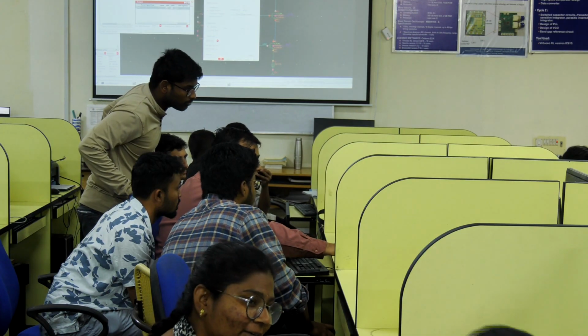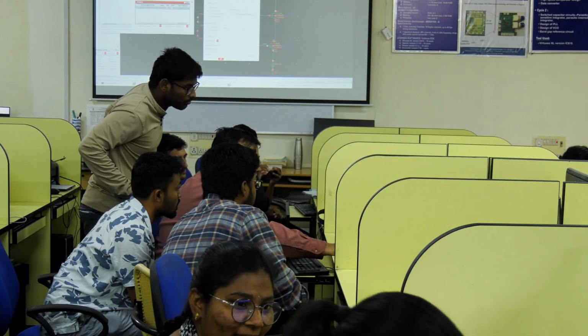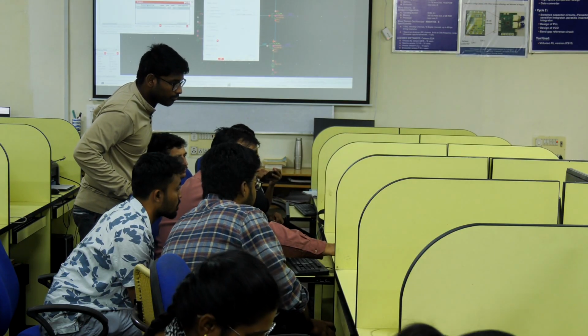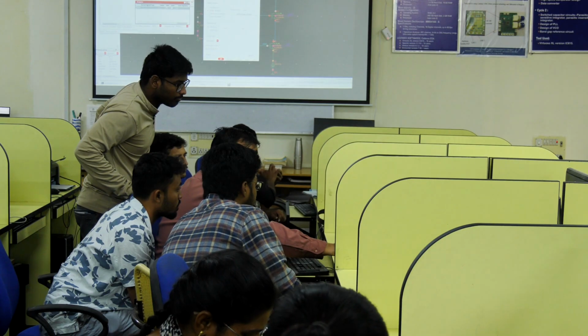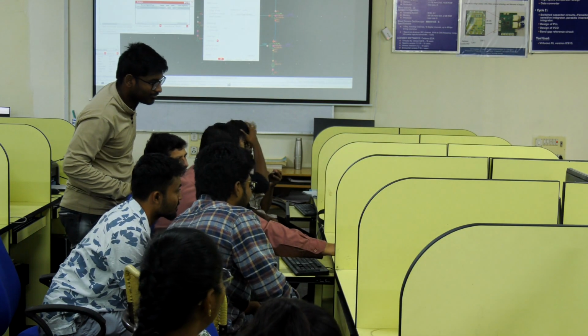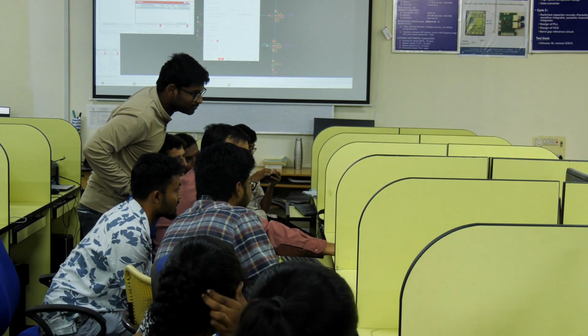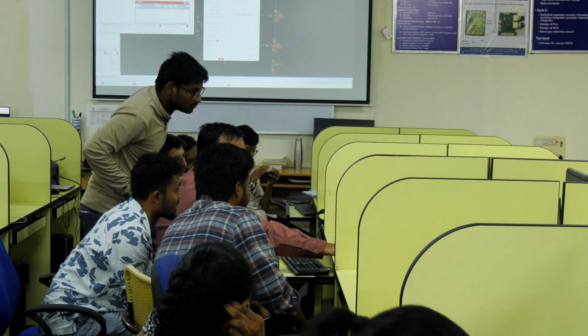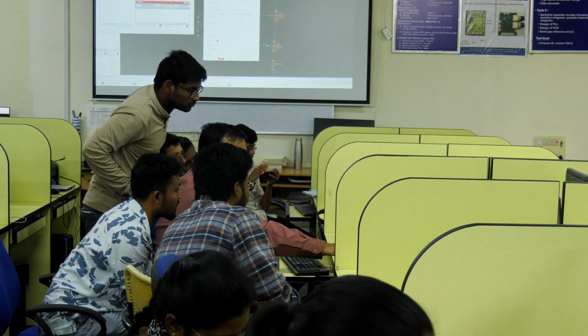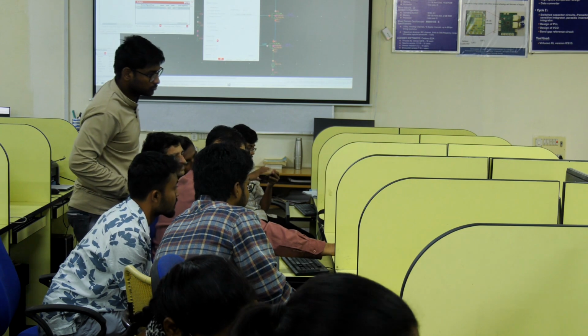At least this says that this circuit can be made. It doesn't say whether this circuit is correct or not. Yes! We have no DRC errors. But it does not say whether this is the same circuit as our simulation. For that we have to do layout versus schematic.